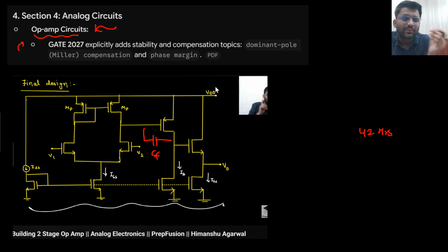When you get into masters, in analog, the initial project that you design would be a two-stage op-amp. There you will be talking about Miller's compensation, drawing the phase plot and the Bode plot, and then commenting on the phase margin. Your target would be to get the best possible phase margin, roughly around 75-76 degrees. I don't think at BTech level they will be expecting that much.